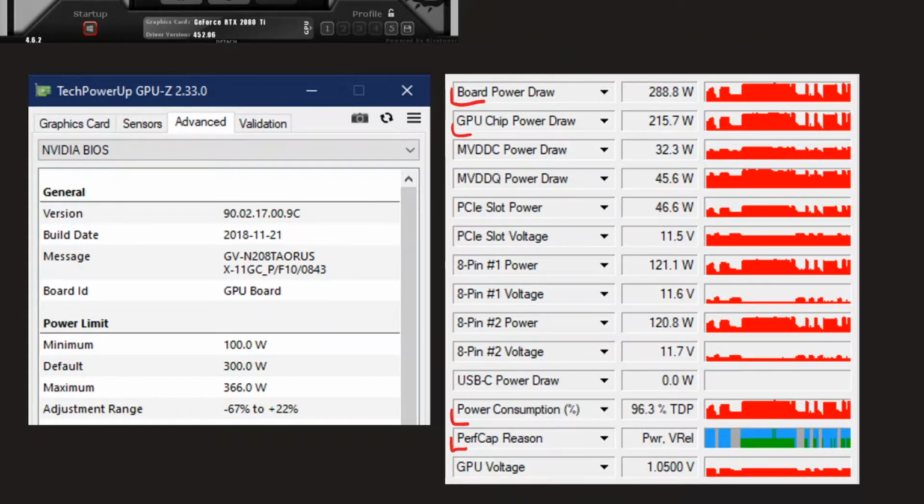And yeah, so always max the power limit, because that's just free performance. Of course, don't be too enthusiastic with it if you have a weak VRM on your card, or it's running really hot, because then it's not going to give you anything. But usually you can just max that.